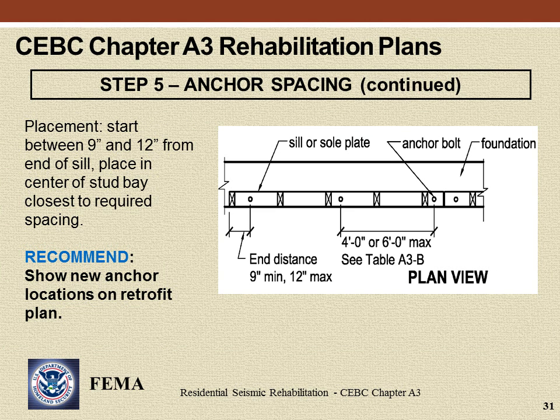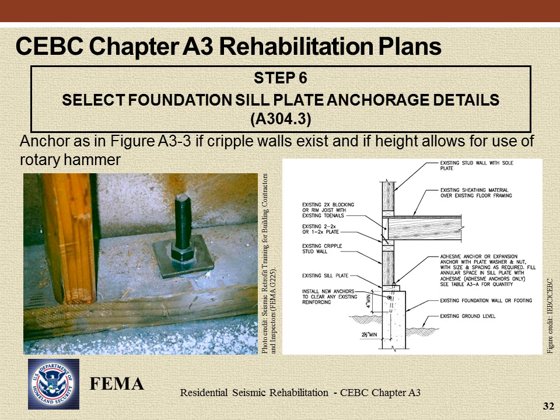This illustration shows a plan view of a foundation and foundation sill plate. End and center-to-center distances for anchor bolts are shown. See Chapter A3, Section A304.3.2. It is recommended to show new anchor locations on the retrofit plan. Step 6 addresses selection of foundation sill plate anchorage details.